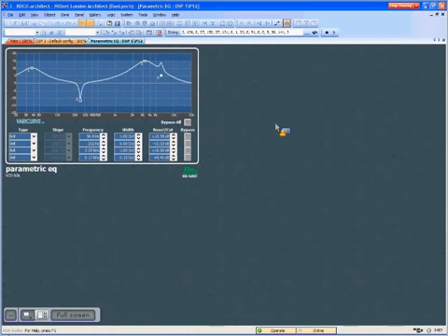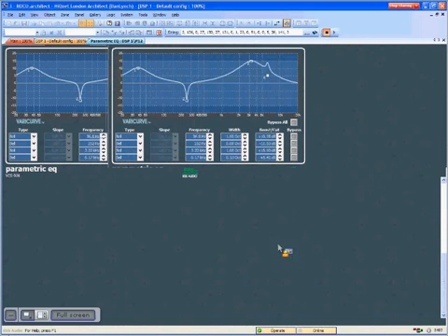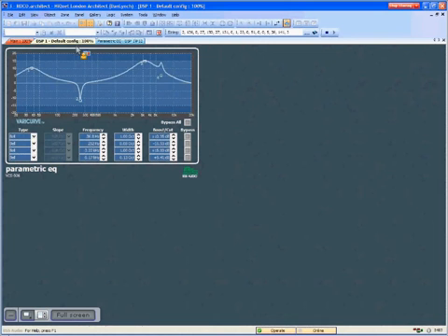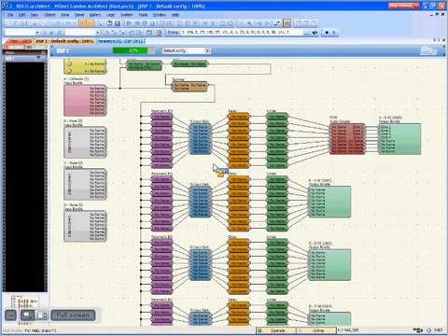Okay, there's my perfect tuning for my speakers. Nice. Well, the problem is, or was, if I wanted that same curve on all of my EQs, maybe the first 8 EQs are all the same speaker, so I'm going to start with the same curve on all of them and then just go tweak it, right? Well, in the past, to copy that curve from one EQ to the next, you had to go out to design mode, right-click, copy, paste.